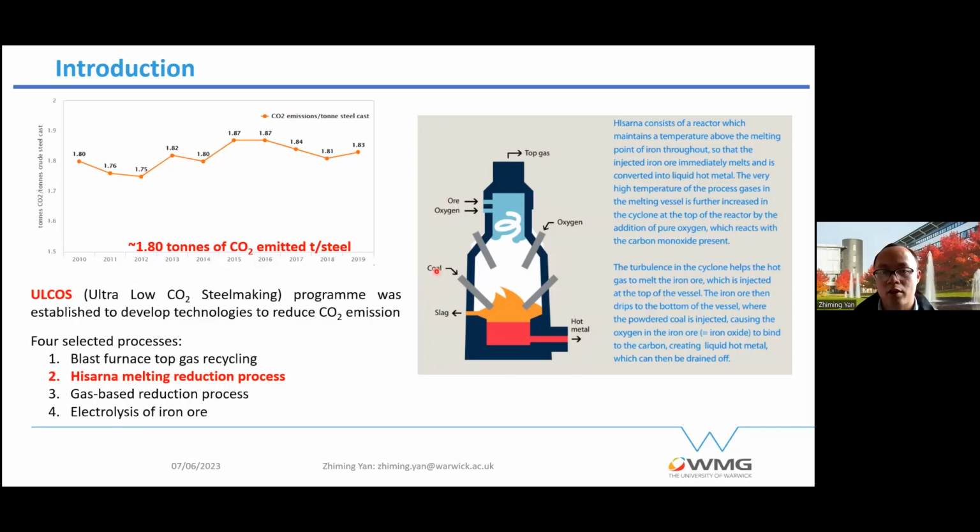We have the coke injection here, and the slag containing the melted iron oxide will be reduced here and produce hot metal. The hot metal is tapped from the bottom and the slag is tapped from here. And here is another combustion lance with pure oxygen to produce the heat required for the reduction, the melting, and all the heat needed for the furnace.